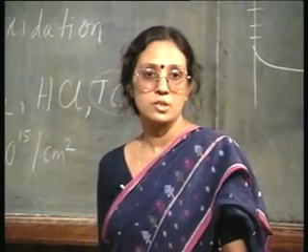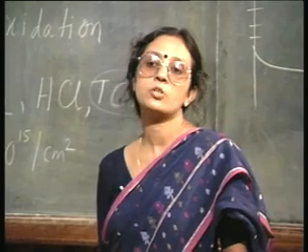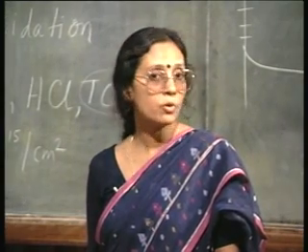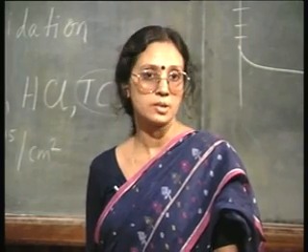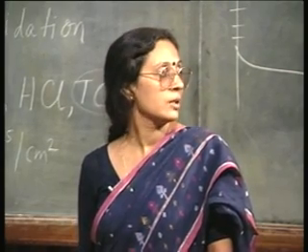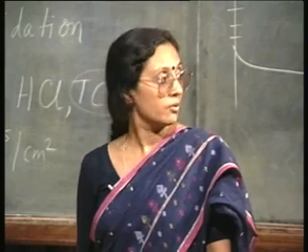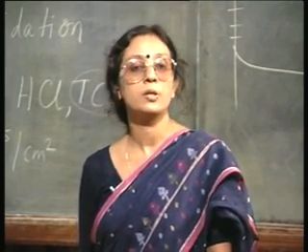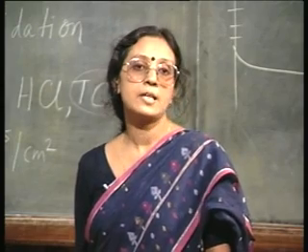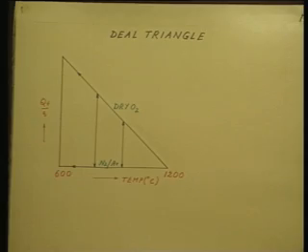Today at the end of the oxidation process, always before taking out the samples, nitrogen flushing for 15 or 20 minutes is carried out. This is done in order to remove the traces of oxygen before the temperature is lowered, so that when finally the temperature is lowered, there is no possibility of having incomplete oxidation. And by doing that, nowadays the fixed oxide charge density can be brought down to less than 10^10 per centimeter square, whereas if you do not follow this practice, it used to be greater than 10^12 per centimeter square. So, making an enhancement mode NMOS transistor today is not a problem, because the fixed oxide charge density can be controlled.